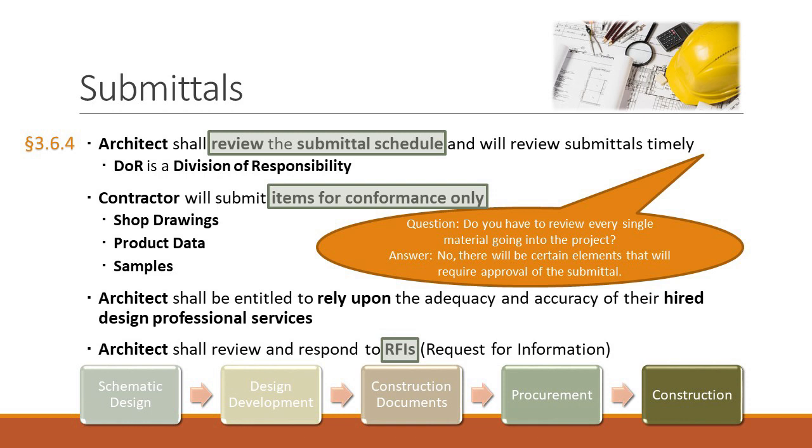Product data and product samples, so they may show you the bricks, or they may show you the history of the data, like I said, the testing of the concrete or whatever. And those are given to you, but only for limited purposes, and this is what the architect's limited purpose is, of checking for conformance with the information given in the design concept expressed in the contract documents. What this means is you are not checking the math.